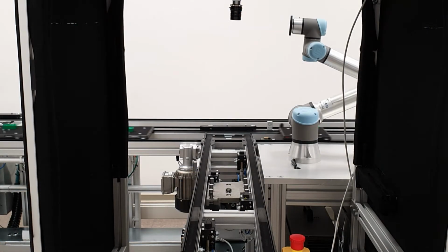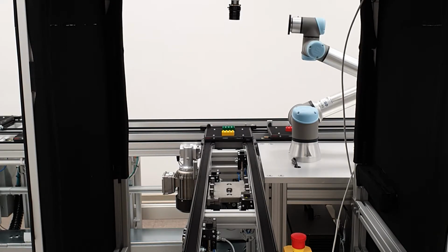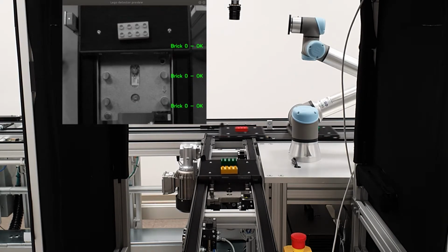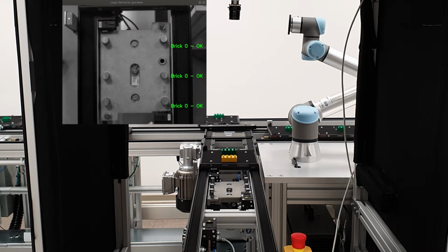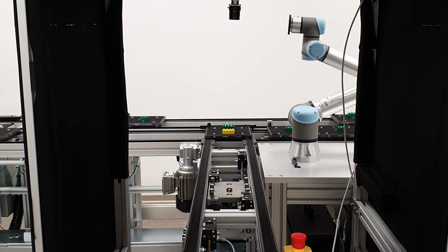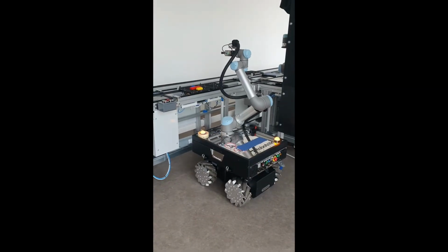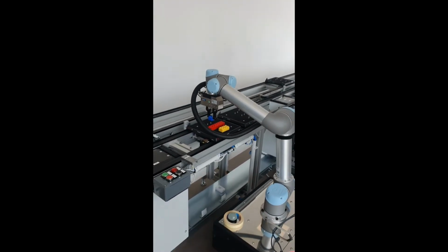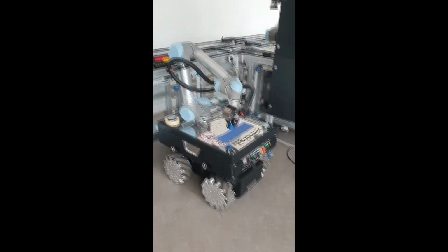The Blazer camera with 60 fps and 2 MP resolution performs product quality control by interfacing with the edge computer. The camera is placed in a specific darkened cabin to avoid lighting noise. It also has an OPC UA server for coordination with other areas. The mobile manipulator takes pieces from the mini pallet and transfers them to the vertical storage, or the waste area if the product doesn't pass the quality control.